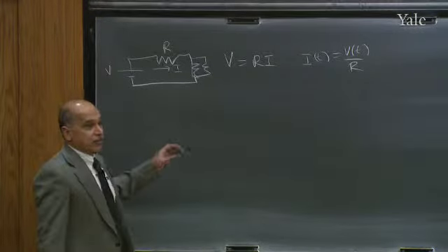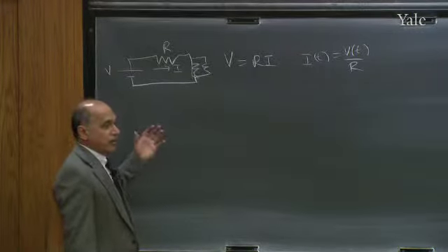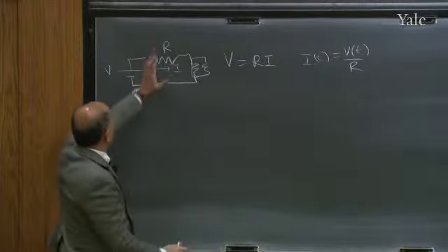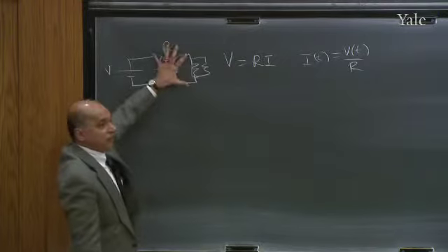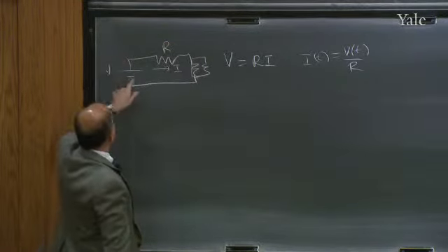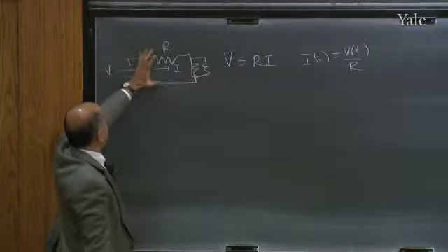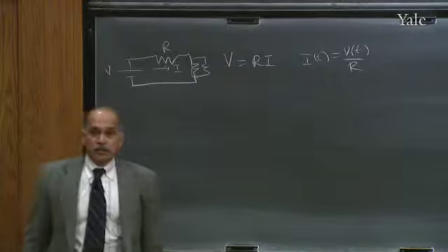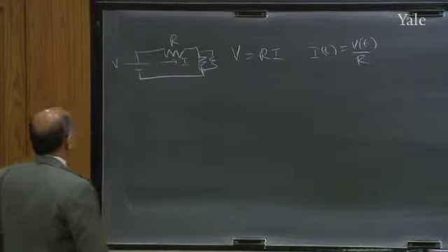It doesn't matter, because in the end we can always combine the ones in series, then lump them with the stuff in parallel, till the whole thing to the right of this is one single effective resistor. Then you find the current coming out of the source as V divided by that. Then every time it comes to a branch, we know how to divide it. So resistor circuits are very easy.